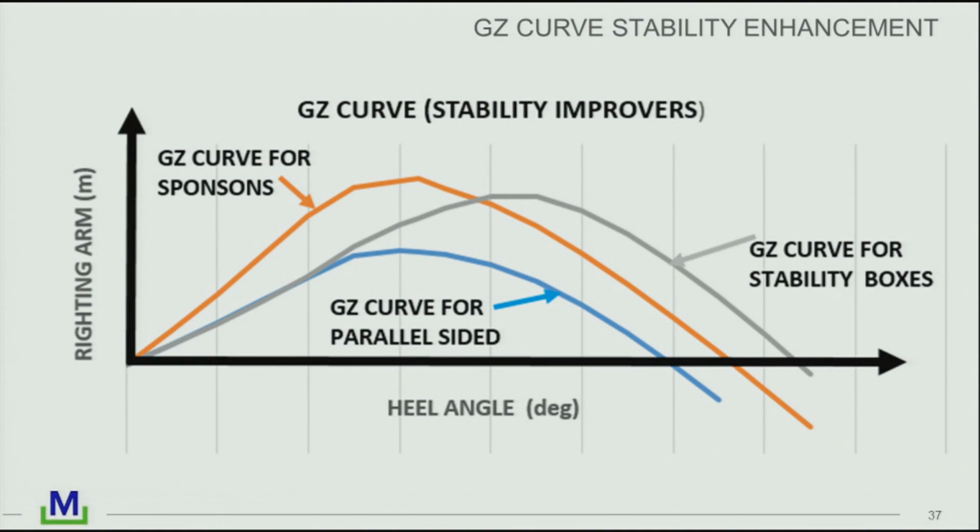So as a general rule of thumb, putting these stability boxes on the deck only enables you to comply with the Marine Warranty Surveyor requirements for stability. But it is odd when you're not actually adding any buoyancy in the normal case. You would think with the roll angles that we get on these vessels, which are quite low, they'll probably never ever get in the water. And again, used once and thrown away.